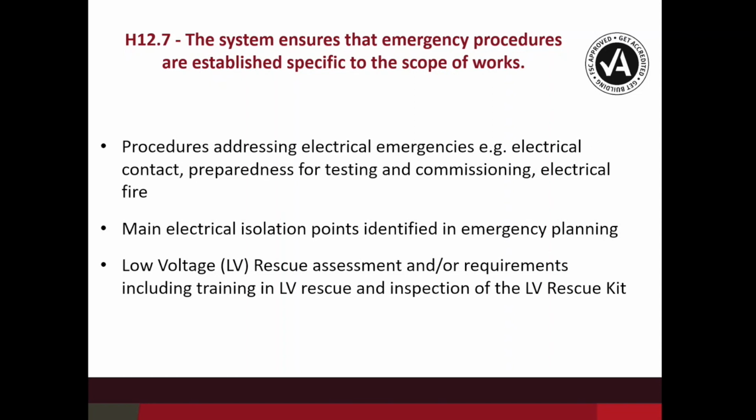In some areas, it is mandatory in terms of, say, switchboards at certain locations and things like that where there are live parts. But again, we then go into, okay, do we have a number of people in that room so that if one person does become energized, the other people can conduct the rescue? So it is really a point of making sure that it's not just, okay, we put down LV rescue kits. There's a whole other space that goes into that where we then expect that the companies make sure that the full planning is completed as required.